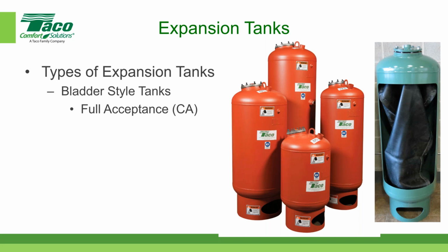Sure. So an expansion tank allows the fluid inside a hydronic system to have a place to go when the fluid expands as a function of temperature change. So typically when we fill a system, it might be in the range of around 50 degrees Fahrenheit. And then if it's a hot water heating system, the fluid, in this case, water or water glycol, would expand as the temperature increases. And if we didn't have a place for that water to expand to, it would break the components inside the system. So the expansion tank allows the fluid to expand and have a place to go.